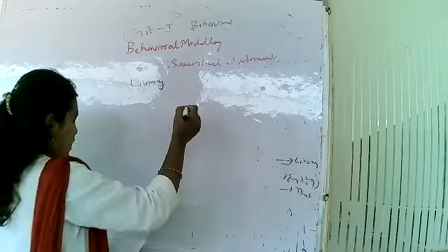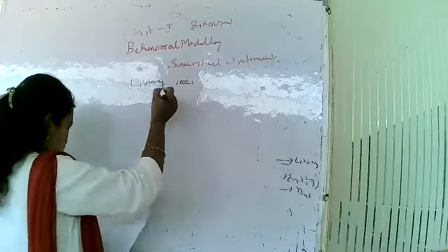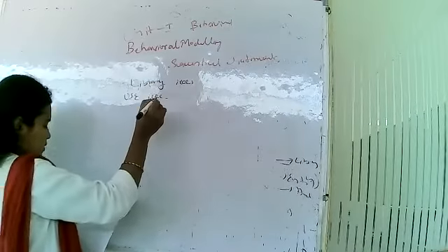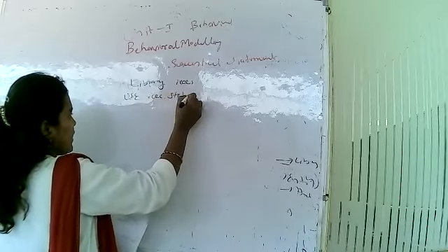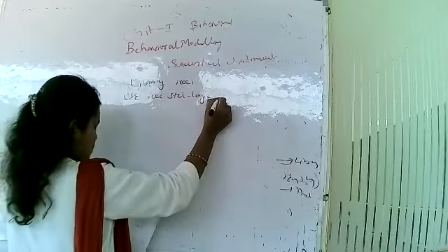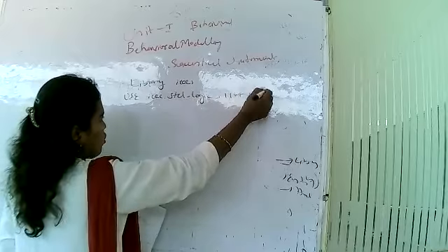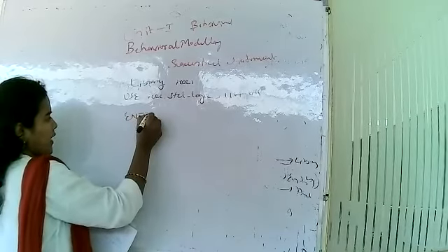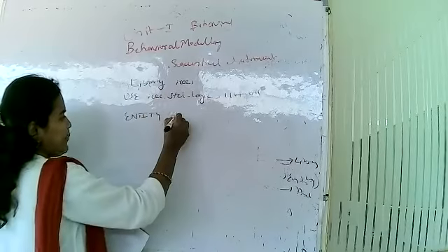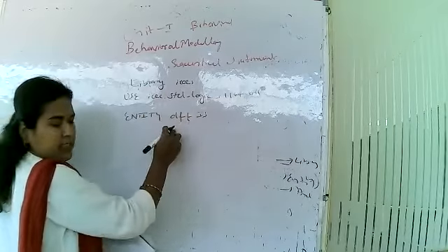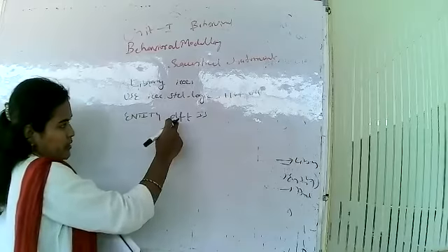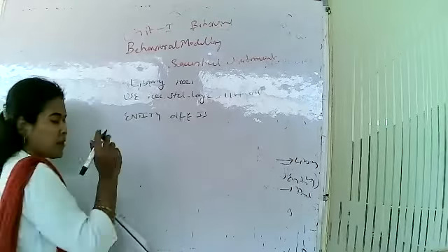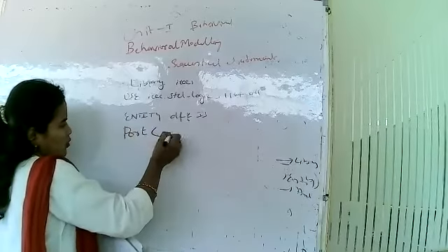Library IEEE; use IEEE.std_logic_1164.all. Next, entity. The entity name is DFF, for D flip-flop, and you have to show the inputs and outputs.